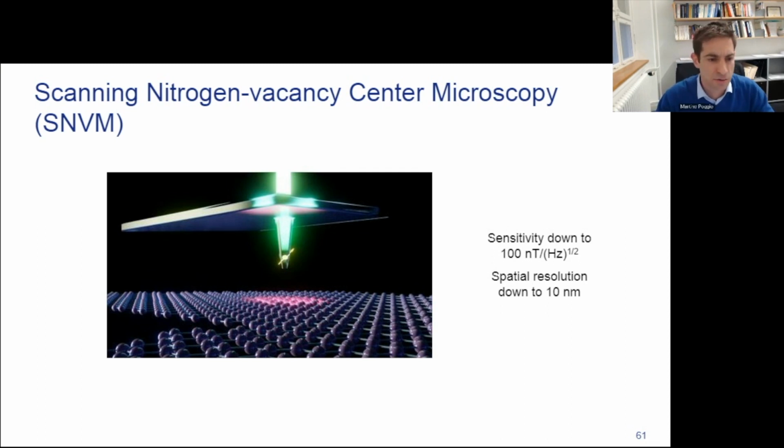Has it been used to measure the stray fields from twisted bilayer graphene? I'm not sure. I think there have been some attempts. Because the sizes of currents that you can pass through there are rather limited, it may be difficult to use scanning NV center microscopy. It is less sensitive to currents than the other two techniques, as I tried to show, and therefore most current imaging that I've seen with NVs involves microamps of currents, and those are rather large for, say, mesoscopic transport experiments.